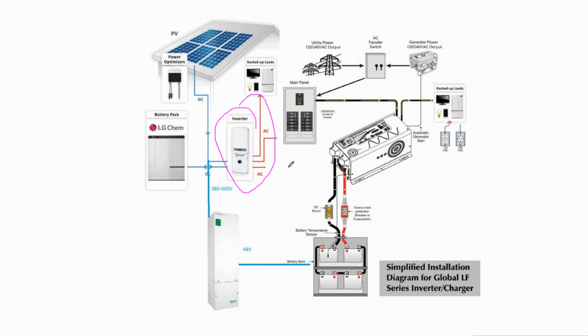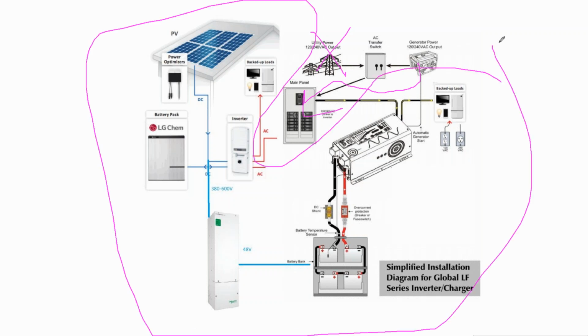Furthermore, you can wire it so that your grid-tied inverter can backfeed to the grid, and your off-grid inverter is just hanging out being used as backup. And then when you're ready to do a full-blown conversion, get rid of the grid, plug in a generator, and then switch into off-grid mode.